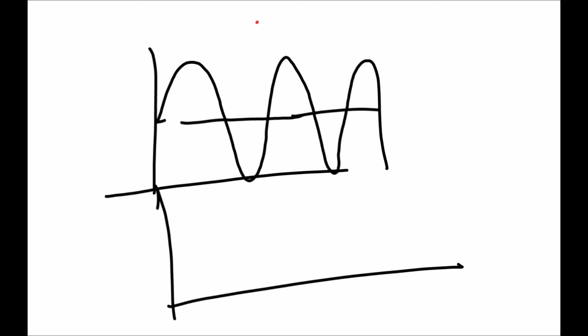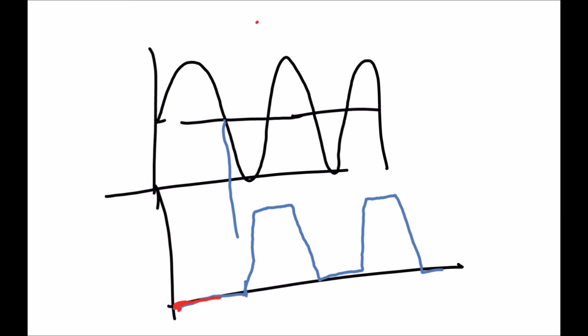So a typical switching waveform looks like this. Let's say that this is our input. So for, let's say this is the inverter, we have in the beginning VDD, then we have 0 until here, something like this, and again something like this. So this is the typical wave of a CMOS inverter. Here we'd say that the switching is somehow earlier, so it will go quickly and then it stays, and then it's pulled down later, but it is pulled down faster. So this is important also to notice.